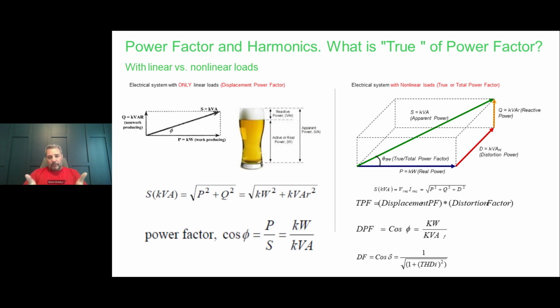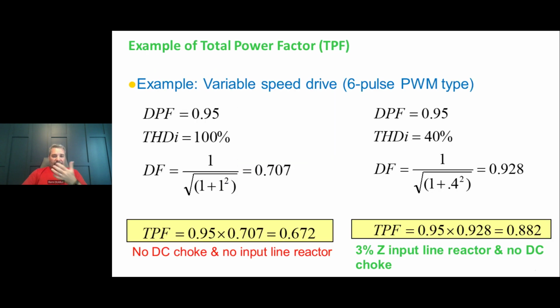To obtain total power factor, you include a distortion factor. The distortion factor, in fact, is due to the amount of high frequency current, referred to as harmonics, that flows in our network, which creates a further displacement on the power factor. So that's, let's say, the true view of the power factor on the network. You multiply your displacement power factor times the distortion factor, and that will give you the total power factor on the network. To understand this a little bit better, I got an example.